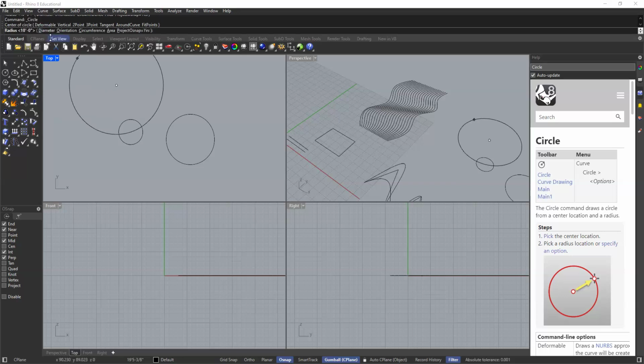I'm going to go ahead and click, and now my options change again. Okay. I can specify the diameter by clicking here. I can even specify the circle based on the circumference. But let's go with the diameter, and let's say now that the diameter is 15 feet, right? So you could always, or not can, always check your options that pop up in the command line. Now, again, for my Mac users, those options still exist for you. They're just going to show up over here on the left-hand side.